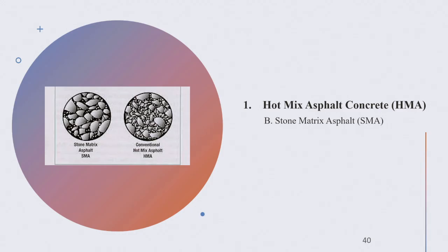And again, the reason is that the coarser the aggregate, the more prone it will be to expansion and contraction with thermal or temperature changes. So with such an aggregate type, if you overdo it, it will be good for rutting, but then expansion and contraction will end in cracking. By the way, that is a selling point for roller compacted concrete.